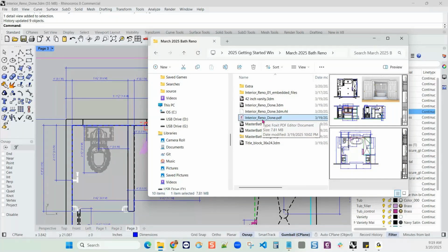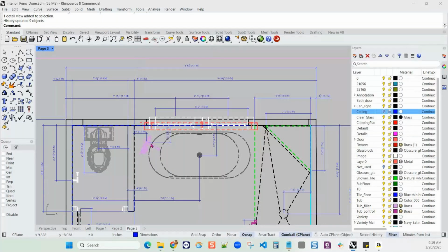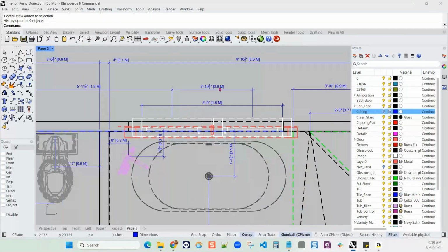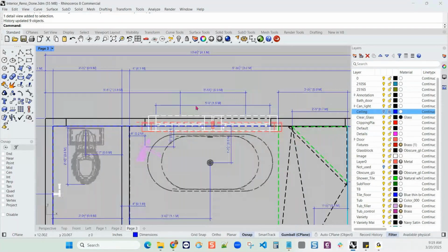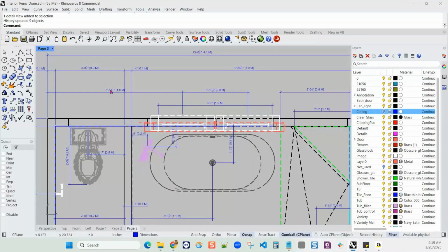So just because this model is in inches, and you can see that down here, doesn't mean that I can't specify distances here and dimensions in the unit system that I'm most familiar with. And for you, if that's meters, that's why I've included the meters for that distance. I will be using feet and inches, but just be aware of that. I will show you how you can use that little decoration on the distance. So if I type in 1.8 m, then Rhino will convert it.